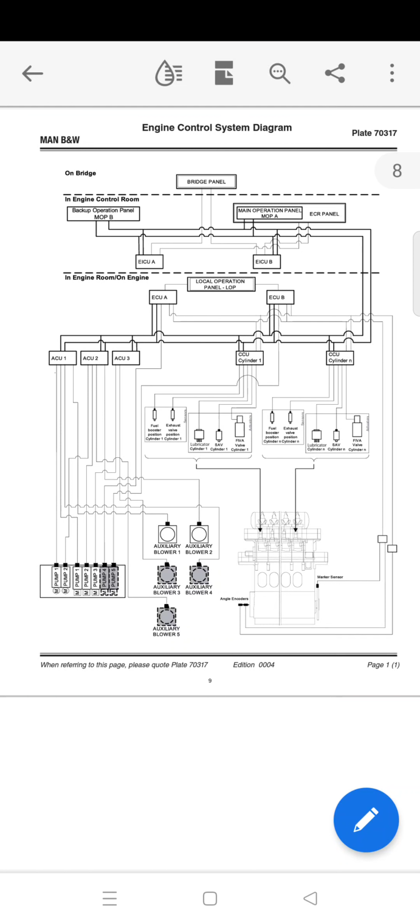Now what is ECU? The engine speed control requires that the amount of fuel is calculated for each cylinder firing. The calculations made by the speed controller are initiated in relation to the crankshaft position so that the execution is started just in time to make the fuel injection. This is controlled by the tacho function. The output from the speed controller is a request for the fuel amount to be injected for the next combustion. This request is run through the different protective algorithms, the fuel limiters, and the resulting fuel amount command is produced. Based on the algorithm of the selected engine running mode, the injection profile is selected.